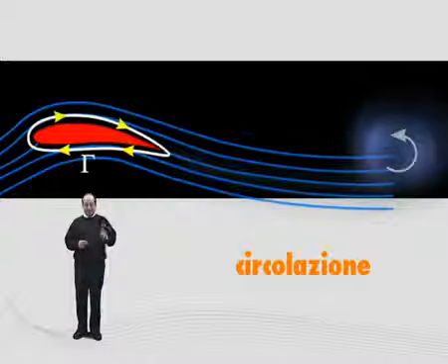Let's remember that the conservation of angular momentum is valid. If the trailing edge is very sharp, both the production of the starting vortex and the circulation around the airfoil are quick phenomena. Every change in the speed or the angle of attack generates a new starting vortex.